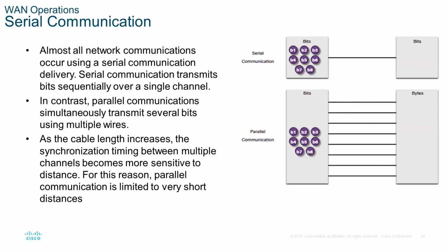Now, what happens with this system is that these bits can be out of sequence. In other words, they're not arriving at exactly the same time. This occurs because there are different physical characteristics in every wire. The resistance, the connectivity, the speed varies because of all the impurities within the media.